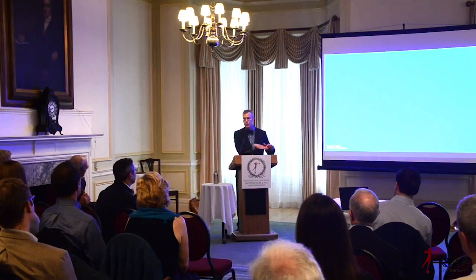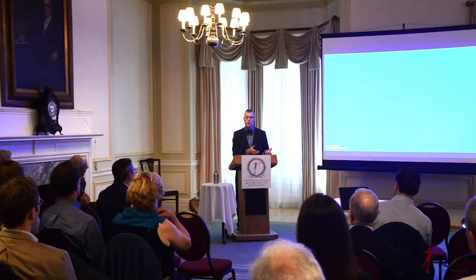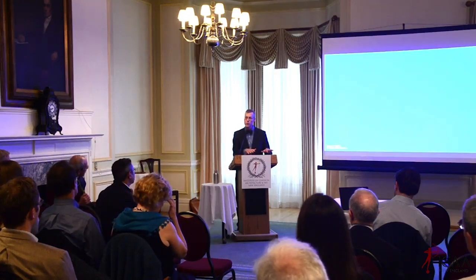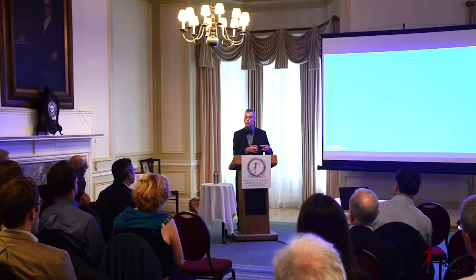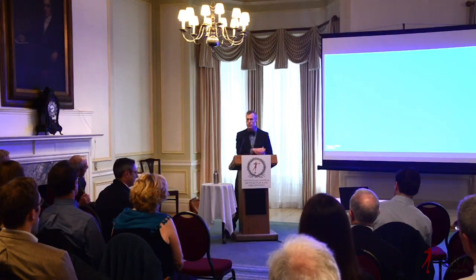Natural pozzolana that you get all around the central Italian peninsula, because of all the volcanic activity from Mount Vesuvius, is essentially a very clayey soil that was cooked by the volcanic eruption. So it's very much akin to brick dust, in that it's clay that's been vitrified. You can pick that up all over the ground as you're walking along. There are two varieties, a very red and a very black, and that's pozzolana.